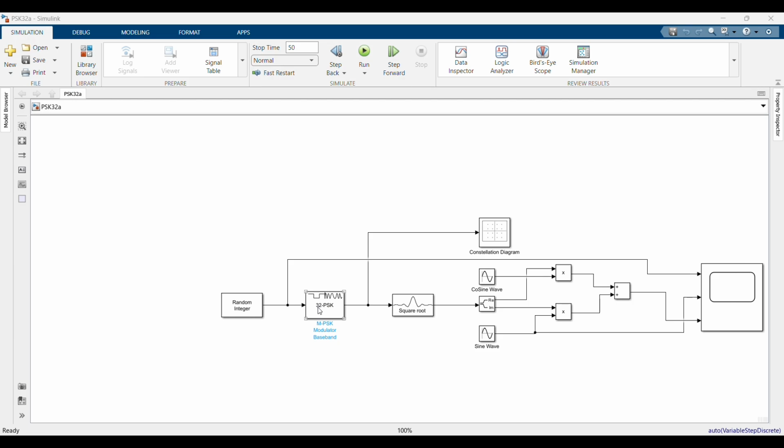Significantly reducing the bit error rate or BER in noisy environments. For the offset, notice the offset of pi over 8, or 0.3927 rad. This rotates the entire constellation, which can help in avoiding zero crossing or meeting specific hardware synchronization requirements. Here we see the resulting constellation.